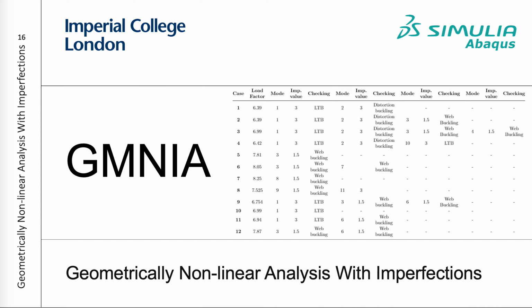Following the linear eigenvalue buckling analysis, geometrically and materially nonlinear analysis with imperfections included, GMNIA, is used in the next stage to verify the strength capacity that accounts for real-world conditions where imperfections may occur during manufacturing and assembly stages. Incorporating such nonlinear material properties allows for accurate calculations of stress distribution, while nonlinear geometry takes into account the reduction of capacity from stiffness reducing effects due to residual stresses and inelasticity.